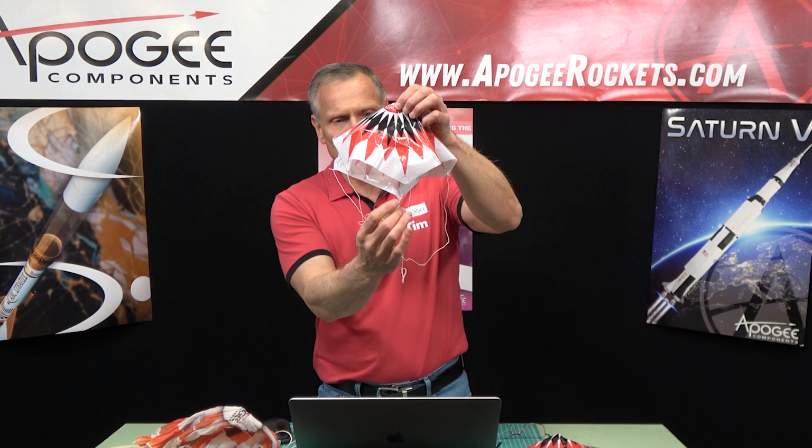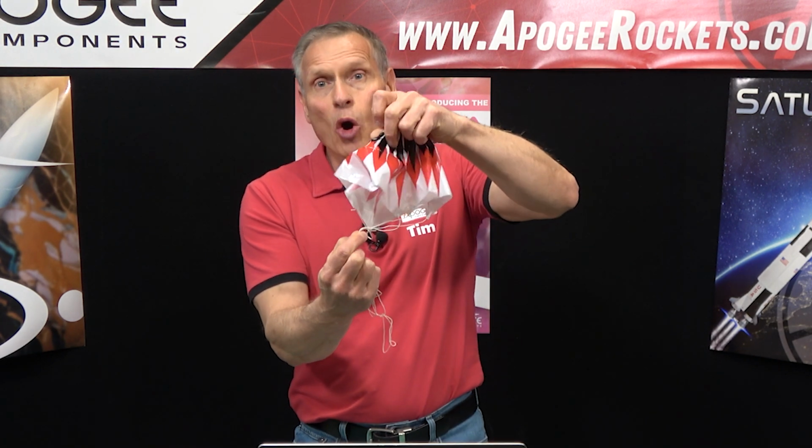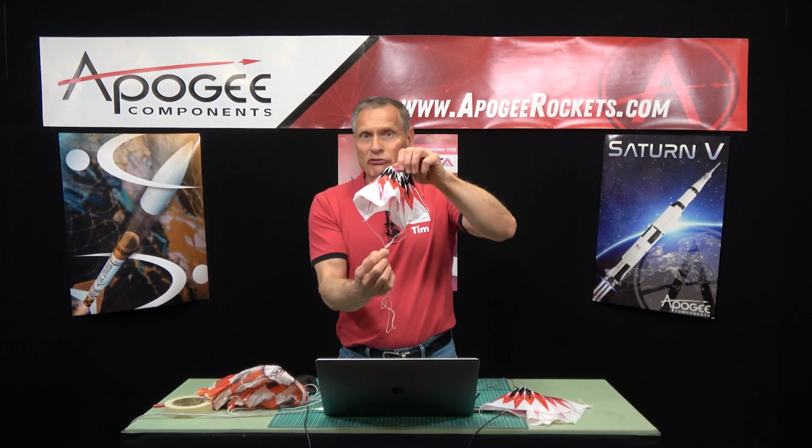Another option that people often do is they'll take the shroud lines on the parachute. So we got the shroud lines here. You'll put a piece of tape somewhere in the middle, and what that does is it prevents the parachute from opening fully. This is called reefing the parachute. It could be a simple way to do it on the field, particularly if you have a nice nylon cloth parachute like this one here.